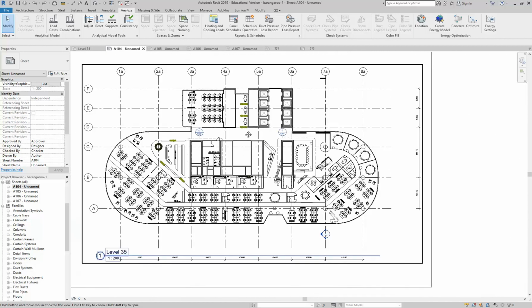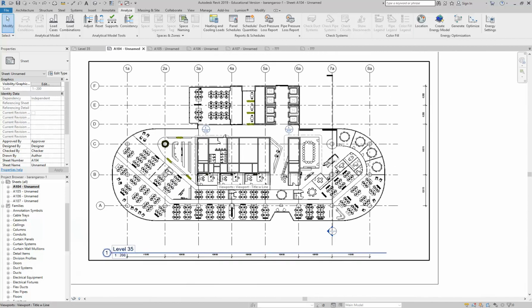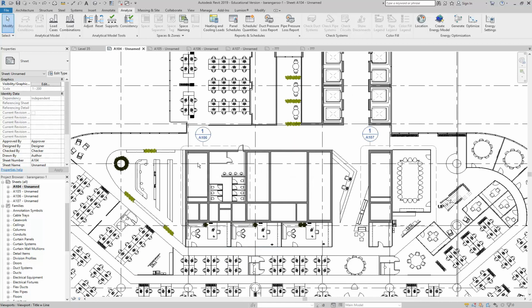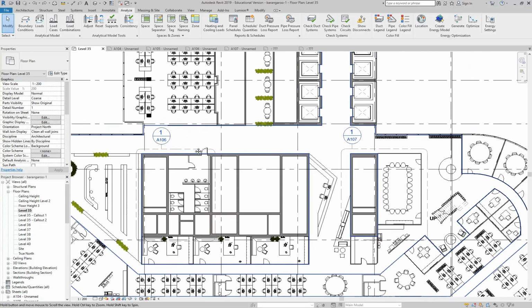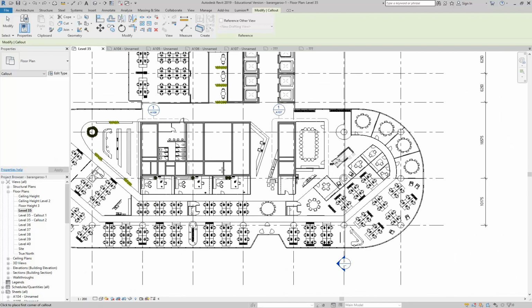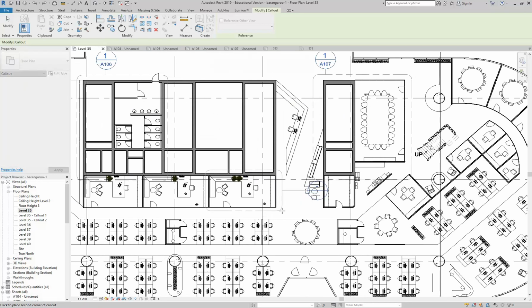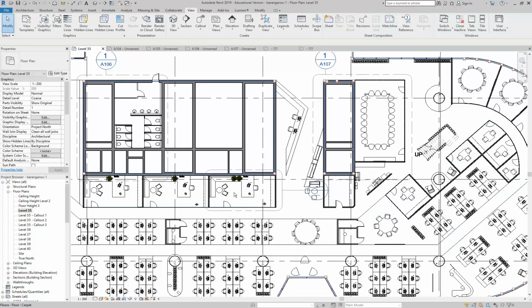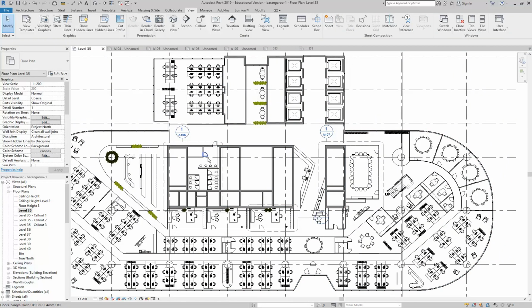Okay, so I've just set up a view on this sheet where I've added a couple of call-outs with some references set up. Is that something you'd all be comfortable with? Setting up call-outs? Yeah, that's right. I'll very quickly say, if you haven't done that before, it's on the View tab. You've got call-outs, and then you simply click and drag to make a rectangle. So I can do another one there. That's right.